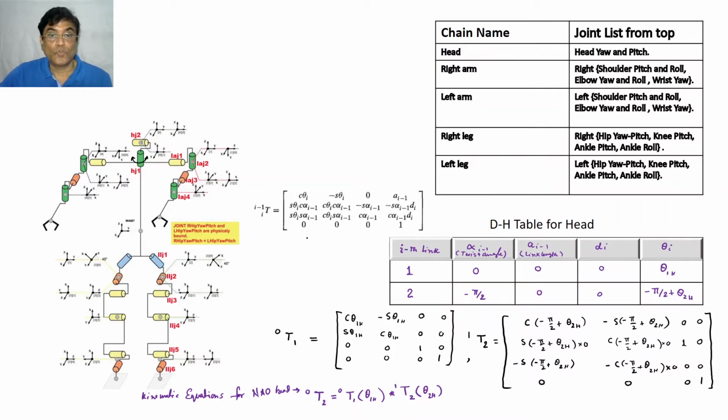And so what will be the model for head? I have the coordinate frame attached correctly. The transformation matrix I have deduced already, see my earlier lectures, and I will just enter all the parameters row wise. They are DH parameters. This is the only variable, okay. With motion, this will only vary. These are all geometrical parameters.